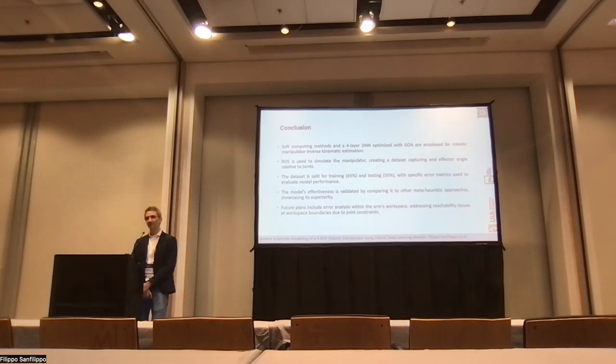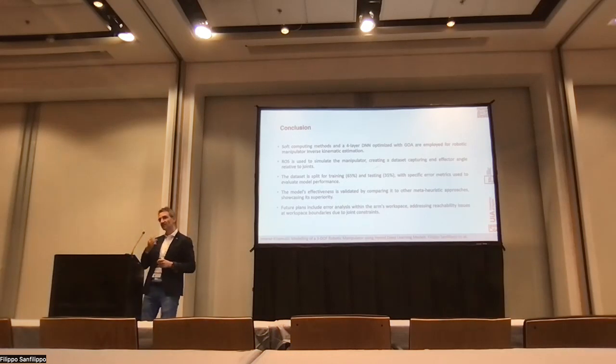Precisely. Basically, we randomly generate 1,000 points, and for each of these we let the end effector reach that point, and then we measure and store the corresponding angles. That's one sample in our data set.